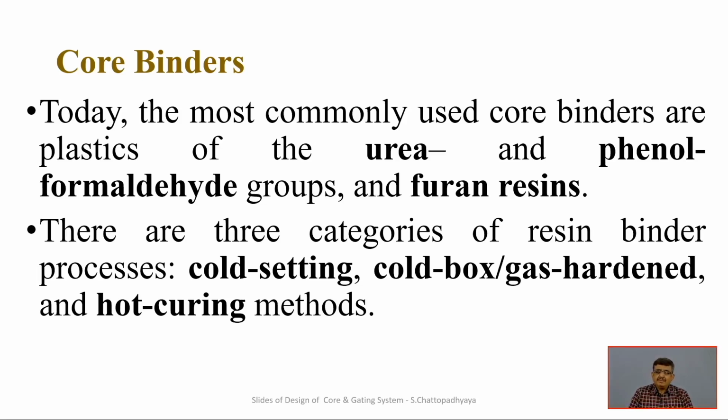Now there comes the question of what binds the core sand. So core binders are also relevant, because the most commonly used core binders are plastics of the urea or phenol-formaldehyde groups and furan resins. So these kinds of organic chemicals act as a binding of those sands with each other, and that is required for the strength of the core.